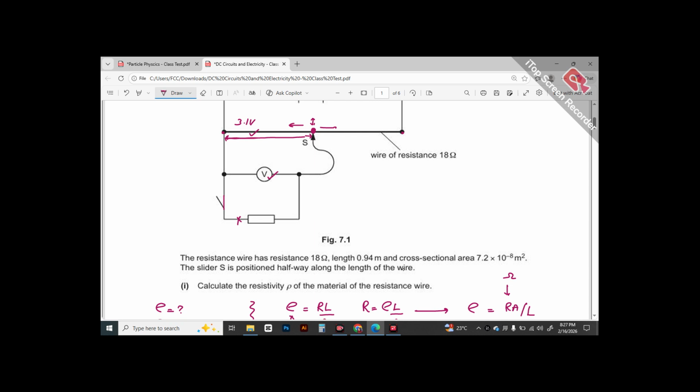So अगर ये voltage drop कम है इसका मतलब है इस वक्त कम resistance है. So you need to increase the resistance ताकि ज़्यादा से ज़्यादा potential drop आए. And resistance बढ़ाने के लिए because हमें पता है resistance is directly proportional to the length of wire, तो मुझे वायर की length from this point बढ़ानी पड़ेगी. In other words, मुझे इस pointer को towards right इस slider को कहीं move करवाना पड़ेगा, but not at this point.